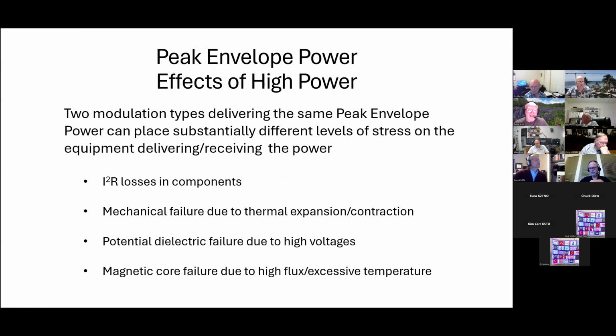So why is it important? All components contain resistive elements. So you have resistive losses in the components. So if you take a capacitor and you pass a large amount of current through it that would be indicative of, say, 1.5 kilowatts, that capacitor is going to heat up.